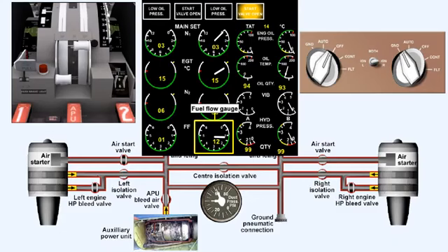Another cause of a gas turbine engine failing to start could be a lack of fuel, but this is fairly unlikely to occur on an engine that was working perfectly when it was shut down. A check of the fuel flow meter when the start lever is operated will give you ample evidence of whether fuel is being fed to the engine or not.